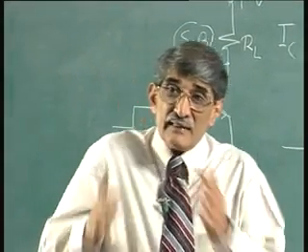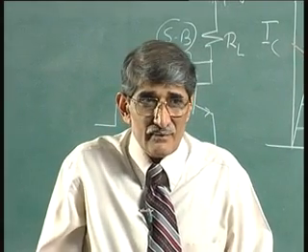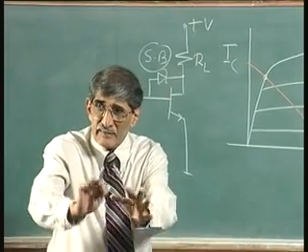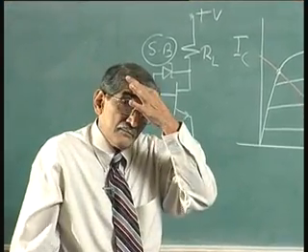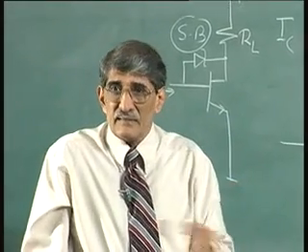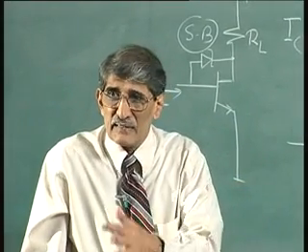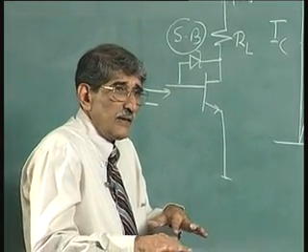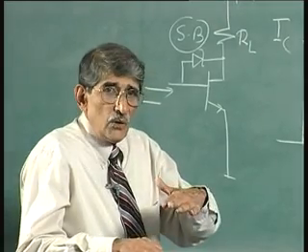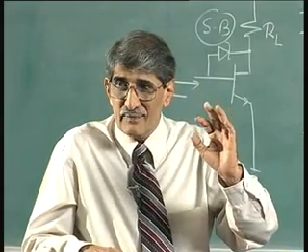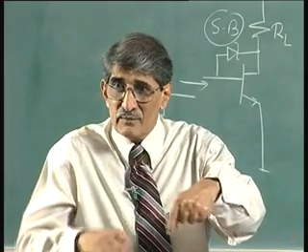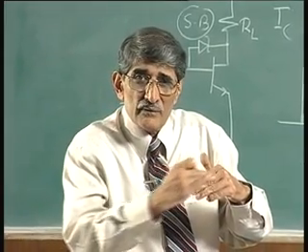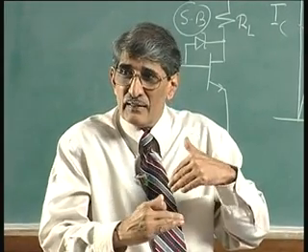In fact, you can actually integrate it along with the transistor. Between the base and the collector, integrate a Schottky barrier diode, or you can put it separately. Make a diode, connect them within the surface, connect internally. The way they do it, I am not getting into the technology right now. This is done by putting a metal over the base region and the collector region. You make the Schottky with the N region collector, you put a metal on the N region, it becomes a Schottky barrier, and allow that metal to go over to the base region, that becomes ohmic.